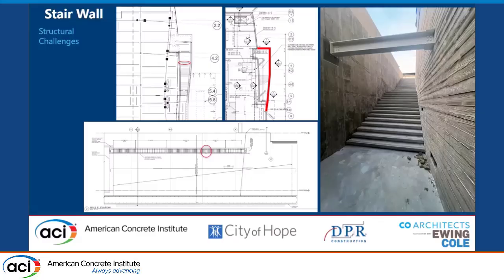I'm not going to go in depth into the structural design, but there was a lot of architectural concrete, so the primary focus will be these 2 walls. This one, and then the one you'll see in a forthcoming slide. Ash mentioned the concrete board form and the challenges of a 20-foot tall retaining wall. This one here is spanning about 40 feet, so we had to introduce an integral bond beam.